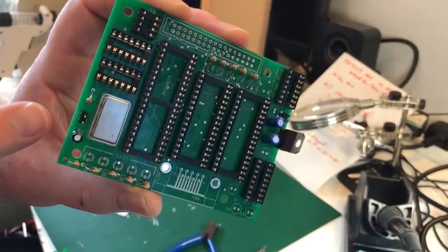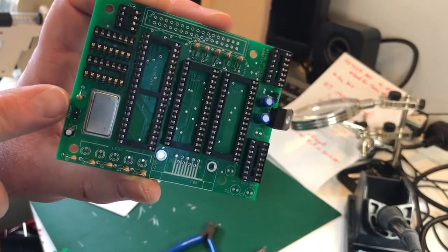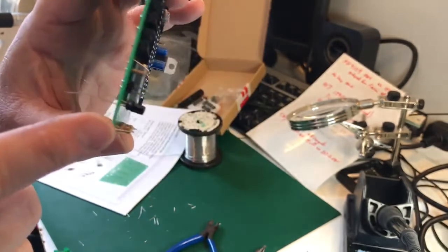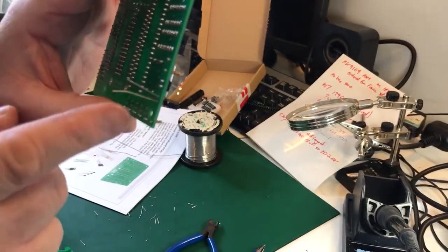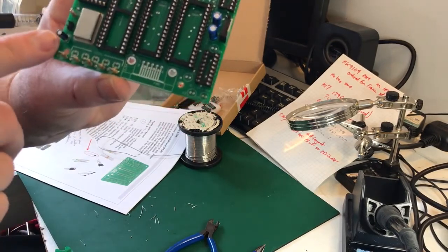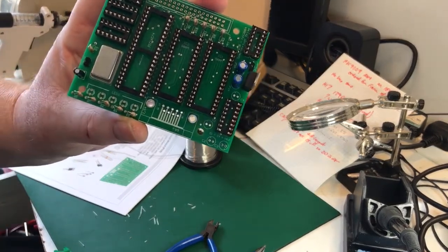So that took me a while to work out. This pin here is ground because it goes to this part of the reset switch connector. It's not marked on here. I assume it wasn't an electrolytic originally. So I think that's basically the positive side down that way. So just in case anyone else is building one of these boards.